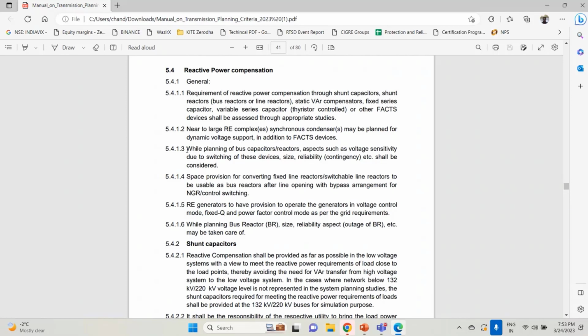And then, by changing the field current, I can absorb and inject reactive power into the system. So it's a device which will be injecting or absorbing the reactive power from the system by utilizing the active power from the system.